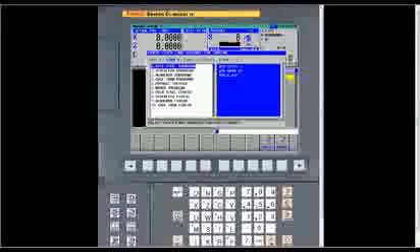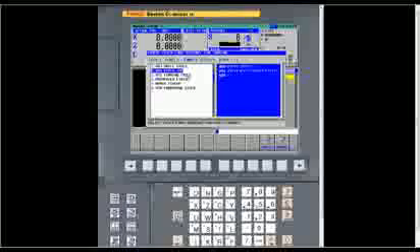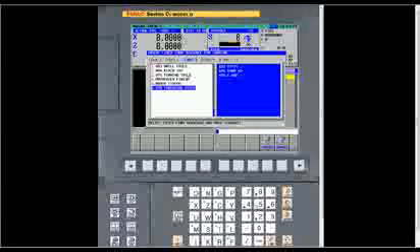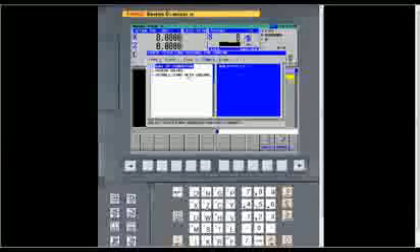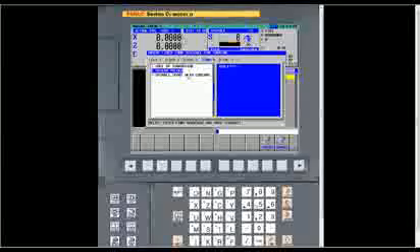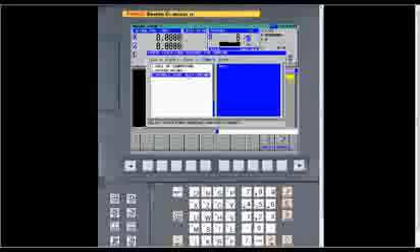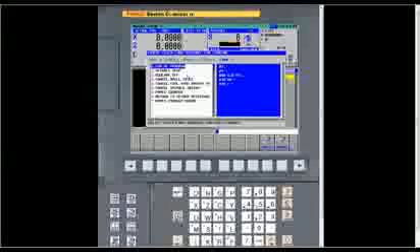As I said, Form 1, these are start of the program type commands. And what I do in Form 2, usually I set up cut speeds for different types of material. As you can see, I've got mild steel, I've got stainless steel, aluminum, cast iron, preheat treated, brass roughing, and then finished feed rates and cut speeds for that also. And number 3, I've got drill cycles, tapping cycles, turning cycles, threading cycles, where if I don't want to use the cycles within Manual Guide I can just go use these, just paste them in. Form 4, I've got calling up subroutine, or do a G10 assigned value type of thing, or just starting a spindle. Form 5 is just end of program.